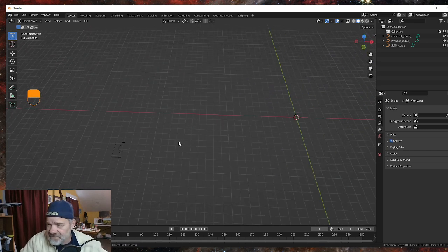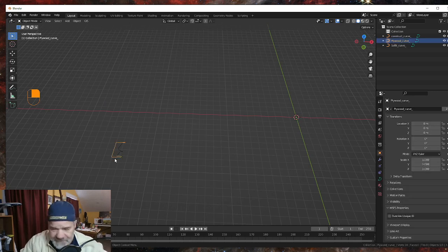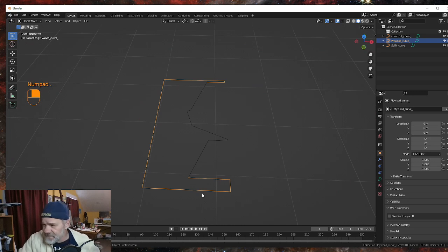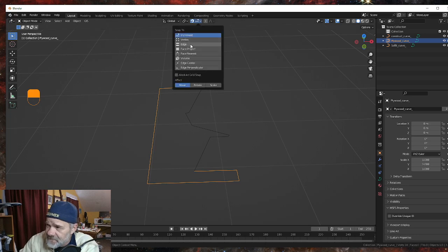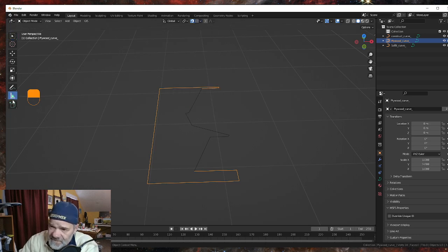when I scaled it in Libre it wasn't at this point. Okay, but let's focus in on this. Now if I come over here to my measure tool, let's turn our snap vertex on. I come over to the measurement tool and I go from here to here. I get that 1.2 meters again. Okay, just like I did when I scaled it in Blender.